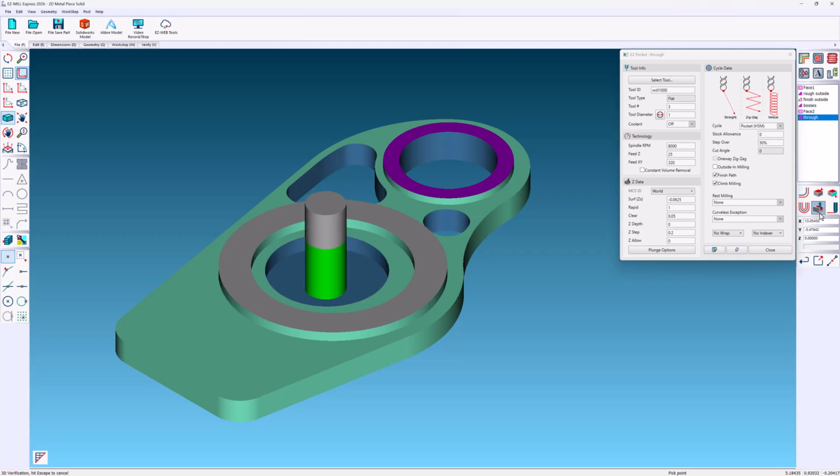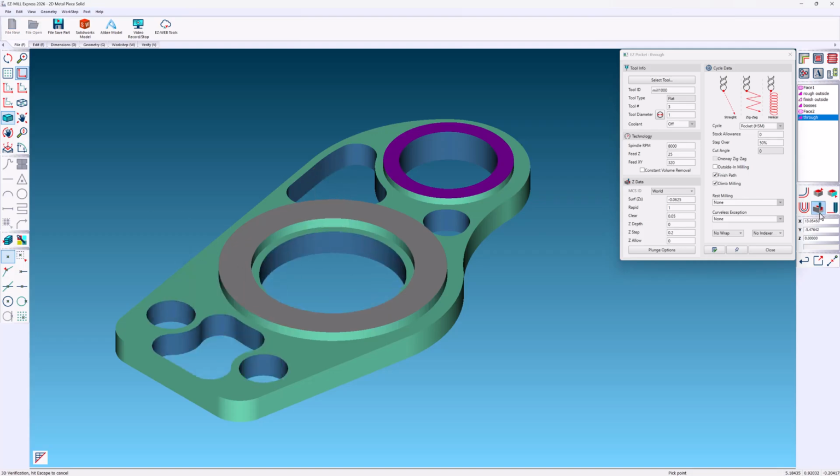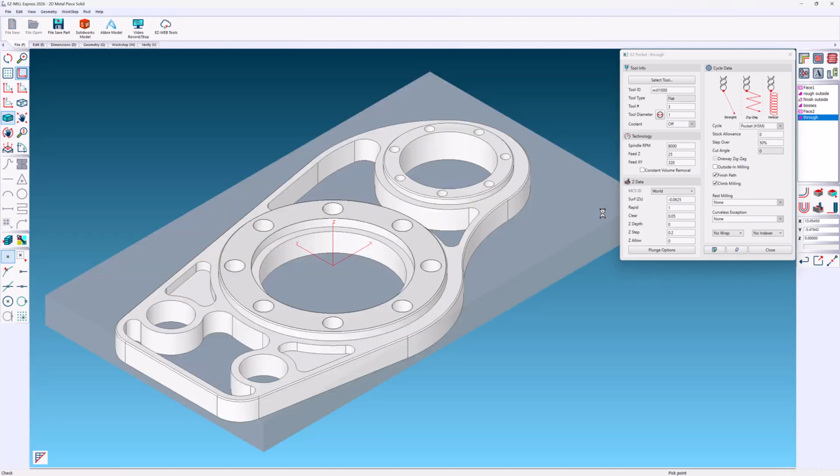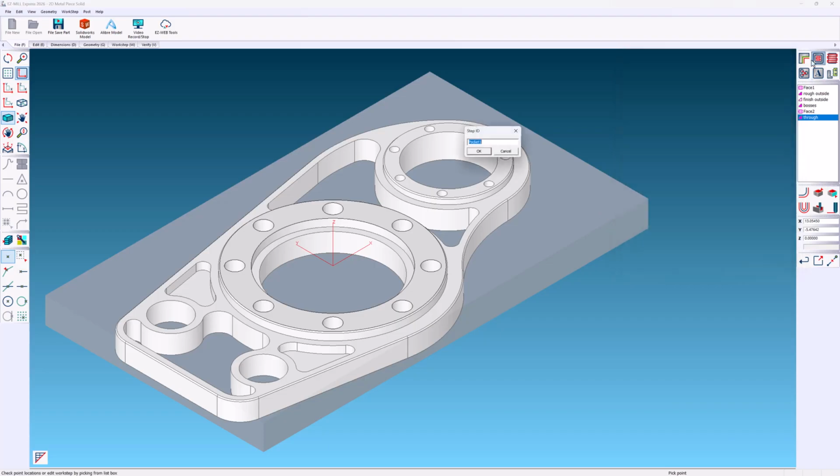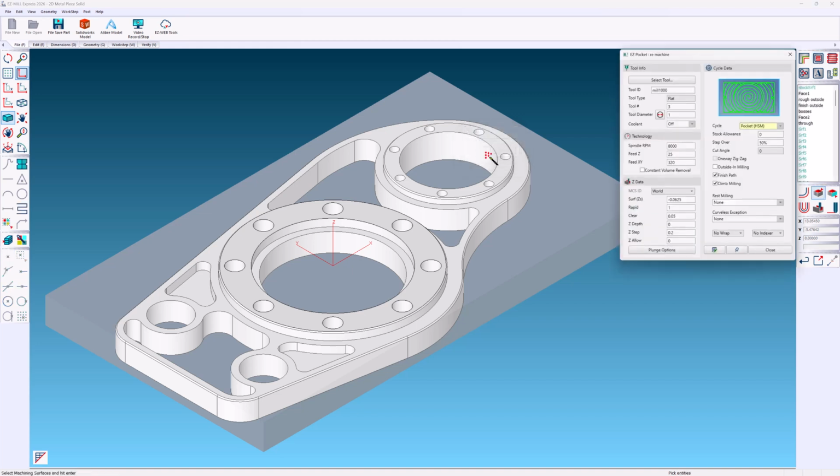As we know, the previous cutter was too large for some of the corners, so we will go in with a re-rough to pick up where the last tool left off. There is enough overlap to give you a quality finish. For rest milling, choose our through pocket operation. And of course, you can change the default Z-step to accommodate the smaller tool.